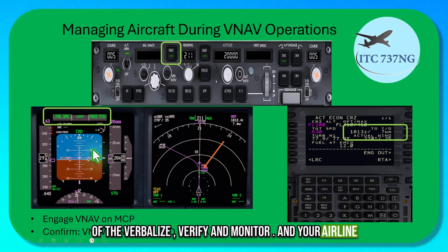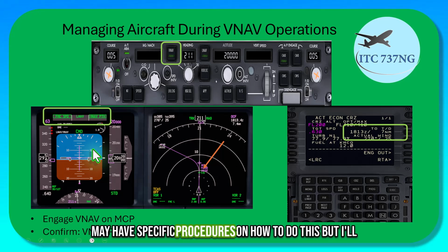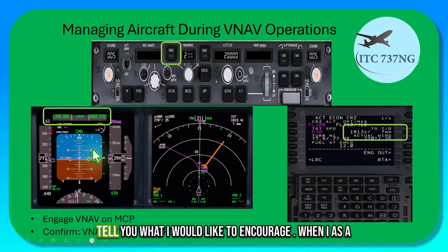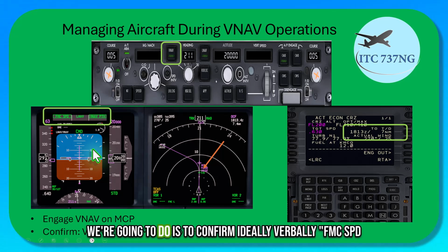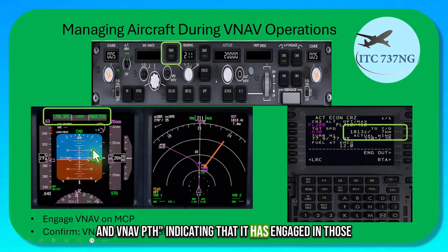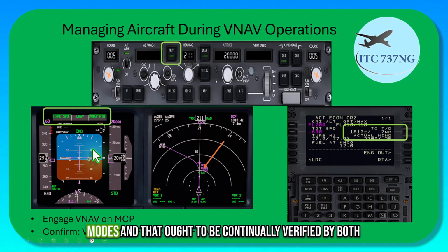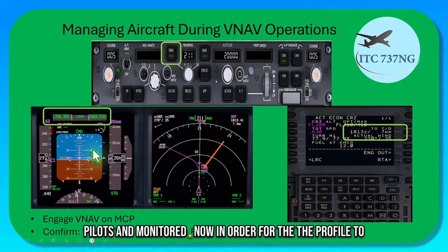Your airline may have specific procedures on how to do this, but I'll tell you what I would like to encourage. When I, as a flying pilot, select VNAV, I say VNAV. And then what we're going to do is confirm, indicating that it has engaged in those modes. And that ought to be continually verified by both pilots and monitored.